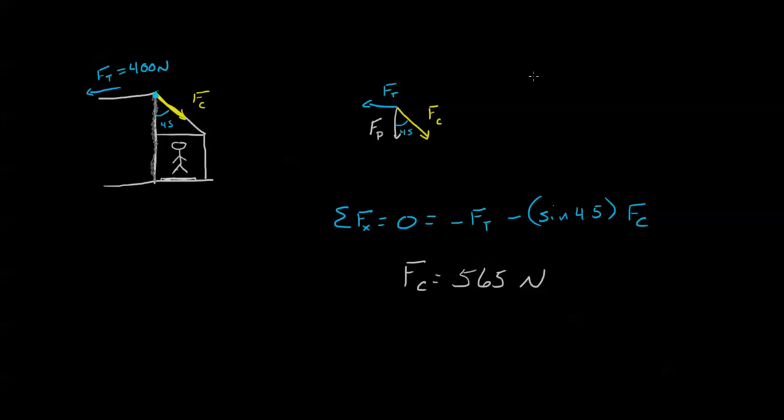So that means that it's 400 newtons horizontally for force of C, 400 newtons vertically, and we're looking for the total force. Now you should know this by now, that's going to be the square root of 2, 1.414. In other words, force of C looks like this: 400 horizontally, 400 vertically. That means we're at about 565 diagonally.